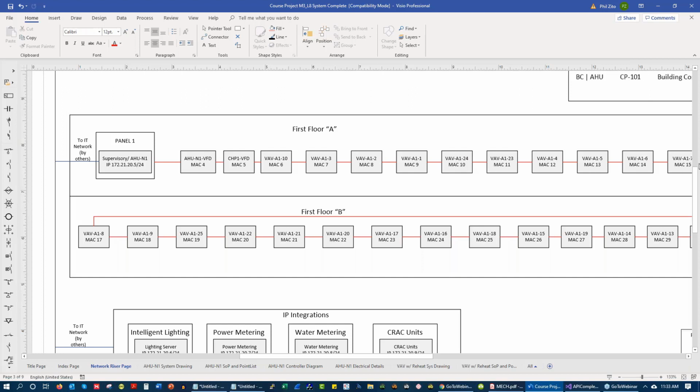You can address everything up front and then install it, or as I prefer to do, I prefer to have the electrician lay this out and then address everything afterwards as part of my, hey, I'm a technician, I'm touching every box, I'm touching every VAV controller. I personally like to do that because it saves a lot of time to poke your head up in the ceiling, touch the controller, make sure that your nuts are tightened, make sure that the floating actuator or proportional actuator is actually properly positioned, all that stuff.